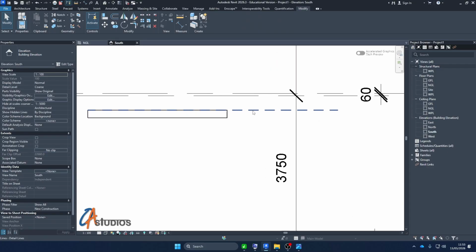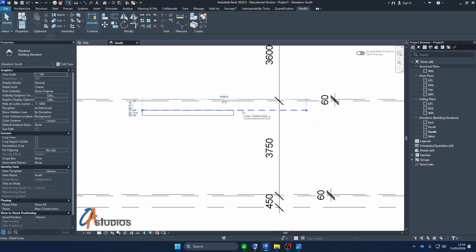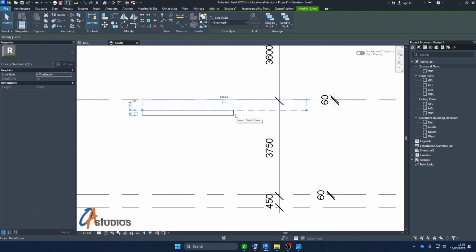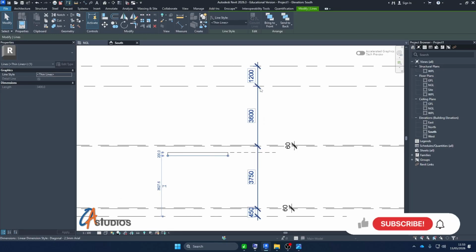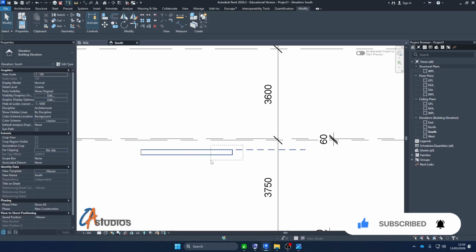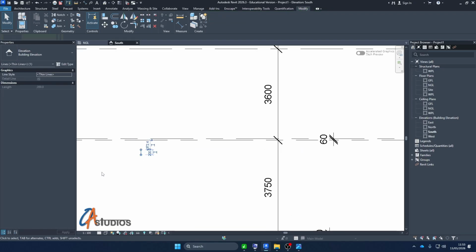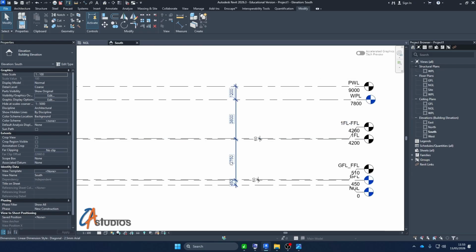Right, so what that means is, if this top is 3750, if you remove the slab thickness, usually of 150, your structural slab to soffit of the first floor slab will now be 3.6. So that's why I've done it this way, 3750. But for here, since you don't have another floor above, we leave it at 3.6. All right, so just take note of that, and I'll delete this.